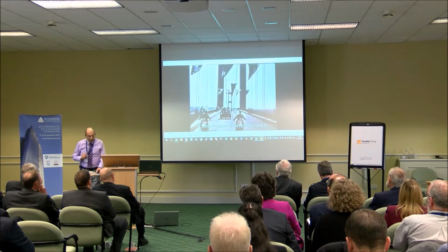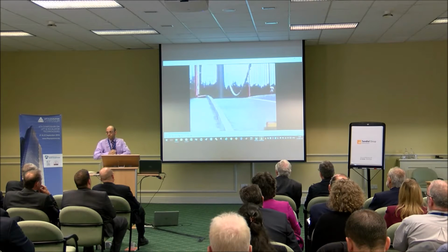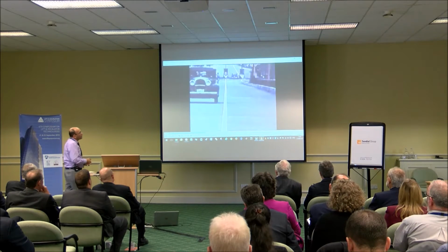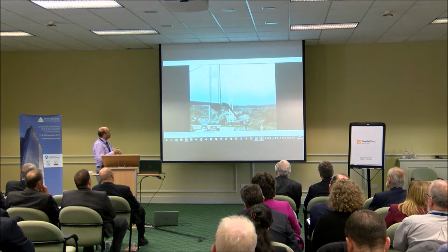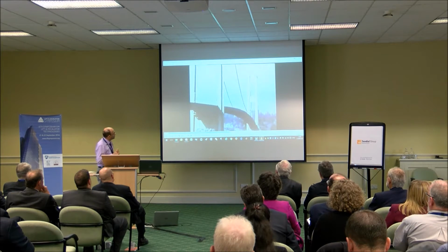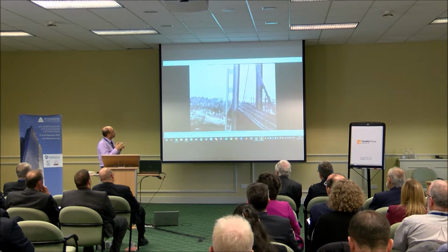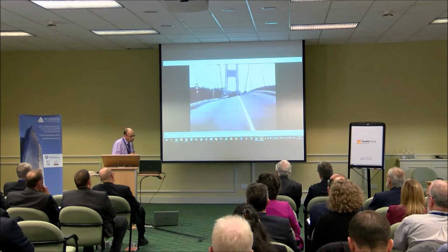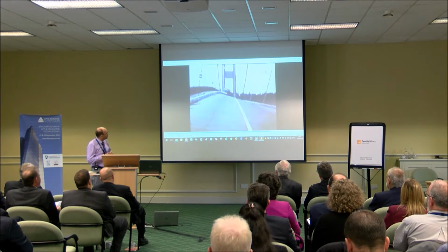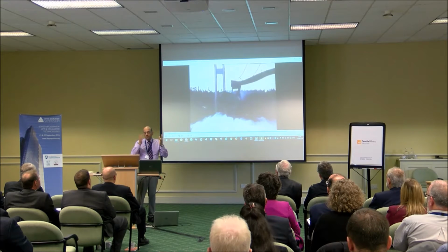This is the Tacoma Narrows bridge collapse. Every student on system dynamics and control theory starts with that. Nothing focuses the mind like the thought of execution. And this is a phenomenon called resonance. It opened, I think, in June or July. In November, the winds got so strong that it caused significant damage. You can see the deviations are increasing with time. There was nothing wrong with the bridge design as such, statically. There was a dynamic problem. Galloping Gertie, I think they called it. Quite significant damage. Obviously, all you need today is a bit of damping. You need to increase damping in the structure.